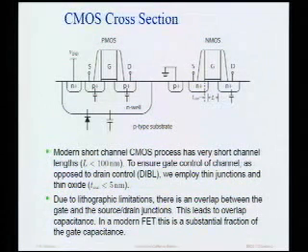And what's happened is we've made the channel length shorter and shorter, that overlap region has become a larger and larger fraction of the overall channel length. That means that the overlap capacitance, or the Miller capacitance, has gotten to be more and more important, and we'll study that in this course. Finally, some other non-idealities. Source and drain junctions are reverse biased junctions, right? So they have capacitance, reverse bias diodes. So on the drain side in particular, if I ground my source, I'm going to have a capacitance at the output. You guys have studied that in all the courses you've taken, so you know that very well.